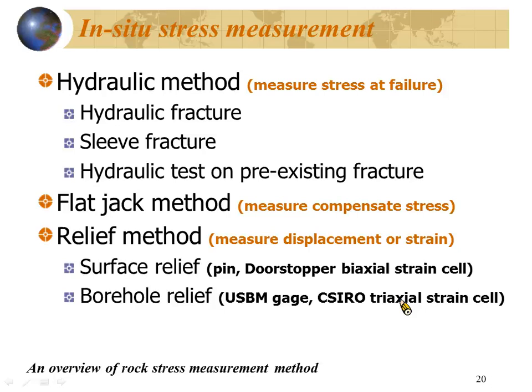Before I remove the stress, I don't know how much the stress is. But I release the stress, the rock will deform, and I apply a stress to make the deformation go back to the original condition. So the stress I apply is a compensated stress for the removed one, so I can use this to evaluate the stress. Can you understand the idea?